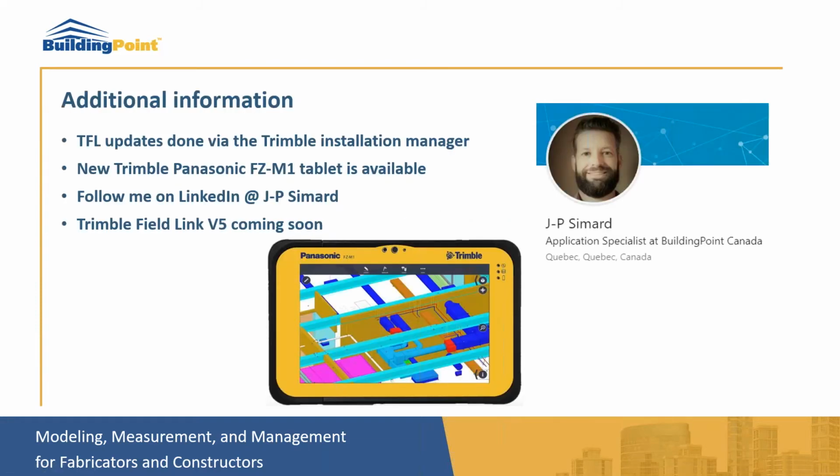The TFL updates are done via the Trimble Installation Manager. By default, this should already be installed on your tablets. If it's not, you can Google it and install it. Once installed, you just need to run the Installation Manager when your tablet is connected to Wi-Fi. The software will seek the license manager on Trimble servers, make sure that your tablet is entitled to the latest version of TFL, and make it available for install. If you're under software maintenance, you will always have access to the latest versions. If not, it will bring you to the latest version that you're entitled to.